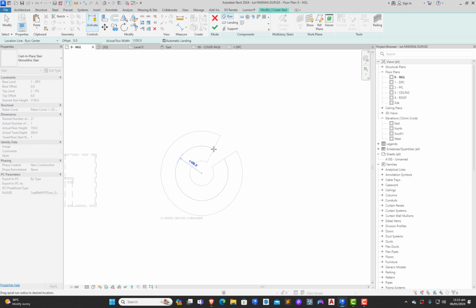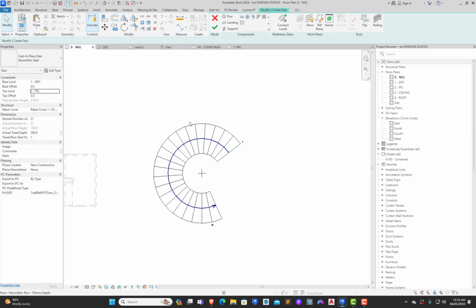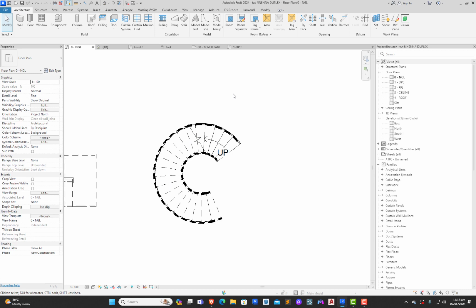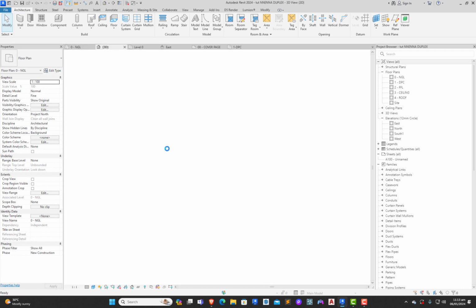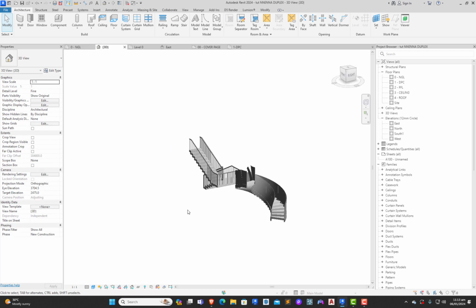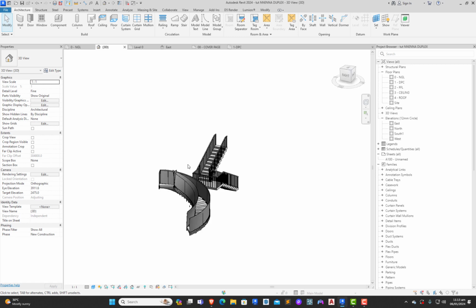however if you want it to be closely packed, we can do that. If you want to spread them out, you can just increase it. You can play with this around till you get what you want, your taste. Then you just click. Revit will automatically draw the stairs for you. Now if you come to the 3D, you can see the stairs you have created.